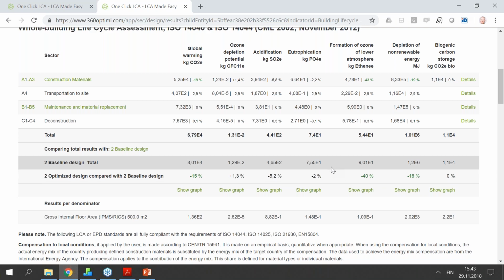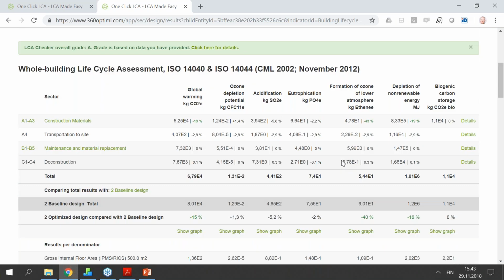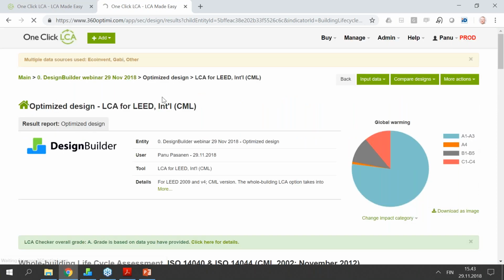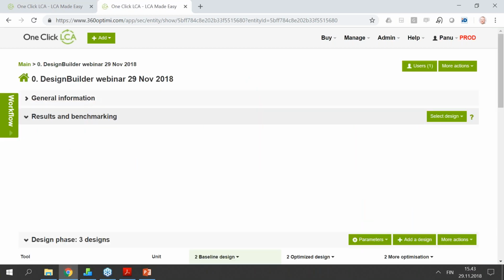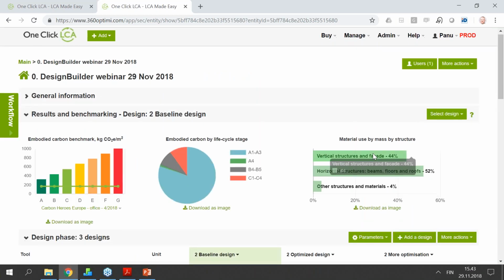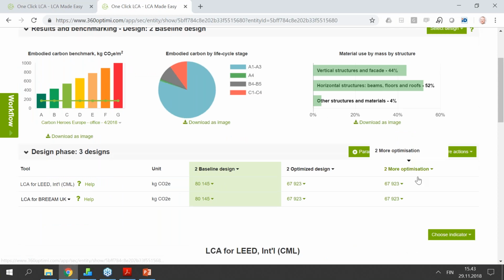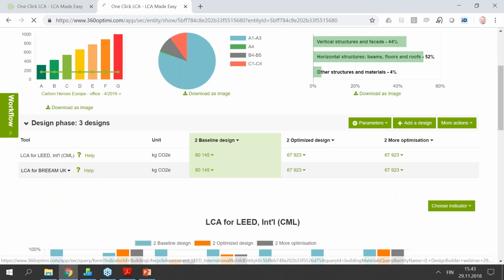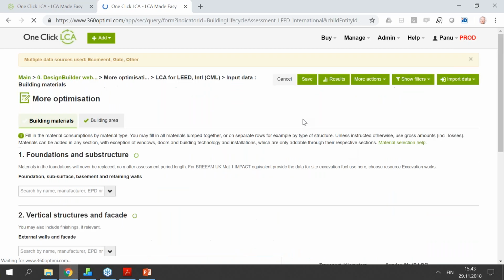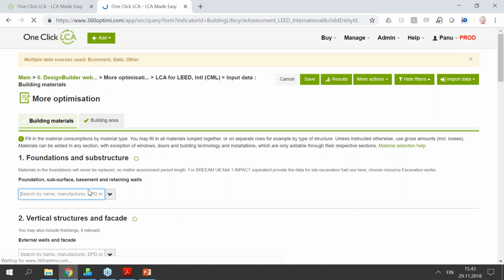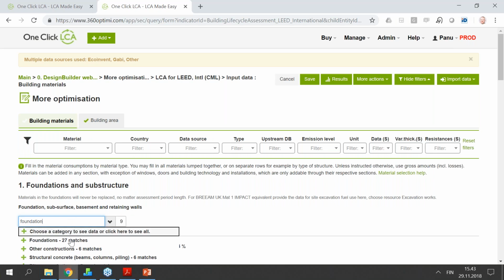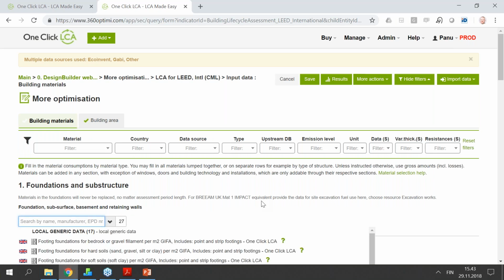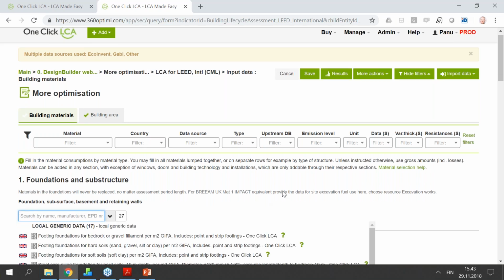Now, if we consider a few other applications, before you could submit an actual project, you would have to make sure that you do have all the structural elements. Right now, we don't have foundations in our model, not modeled for thermal purposes ever. So what we are going to do is add the foundations, for example. And we are going to assume that this is sitting on 10 meters of soil.